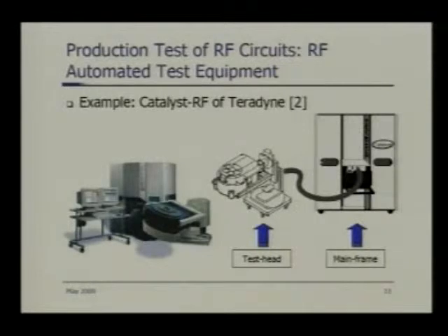And on the test head you place your device interface board, on which you place your device to test. So the test response comes out of the device, goes to the test fixture, comes out of the test head, goes to the ATE, and where you do the analysis.